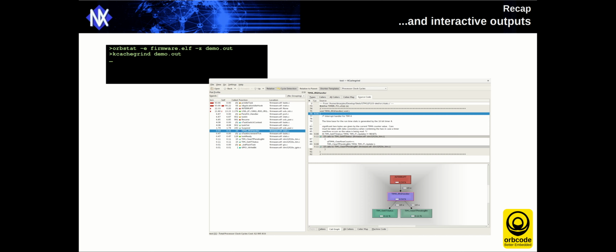So let's look quite briefly at this thing in operation, and rather than using the UART itself, we're actually going to use the new Orbtrace hardware, which gives us, you remember on the orbtop picture I was showing 4,500 or so samples per second. With the new hardware, which I'm going to talk about after this demo, we can get much higher flows, and I think in this demonstration you'll see we're doing about 150,000 PC samples per second.